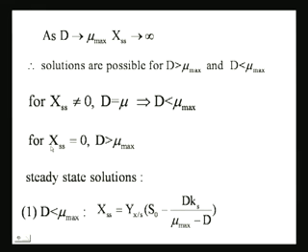What does this physically mean for you? What it physically means is that if dilution is very large, then it will sweep the cells away, it would take the things away with it. So, if D is very large, then the residence time in the reactor is very low, because D goes as 1 over tau. If the residence time of the reactor is very low, it means that the cells are not getting enough time to react and grow. Okay. So, this is the physical interpretation.